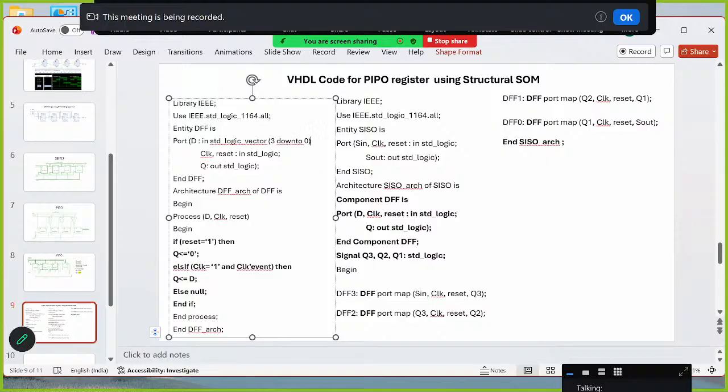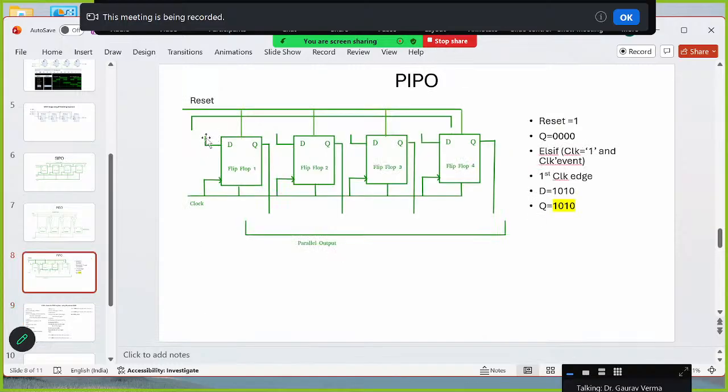Okay, this we need to make is std_logic because these are single bit. Similarly, Q will also be of 4 bit: Q out std_logic_vector 3 down to 0. Why have we done this? Because we know now these inputs are independent, parallel. So we need to apply the input at every D flip-flop.